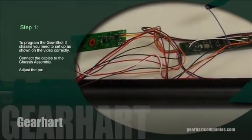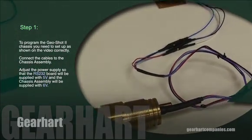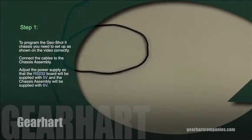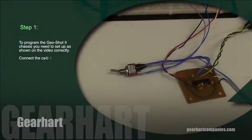Step 1. To program the GeoShot 2 chassis, you need a setup as shown in this video. Connect the cables to the chassis assembly and adjust the power supply so that the RS-232 board will be supplied with 5 volts and the chassis assembly will be supplied with 6 volts.